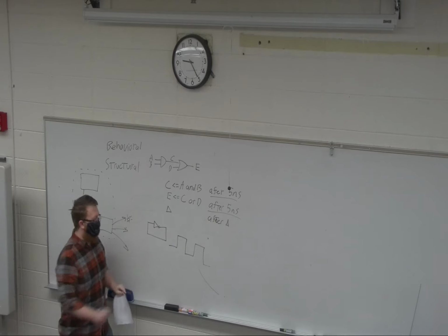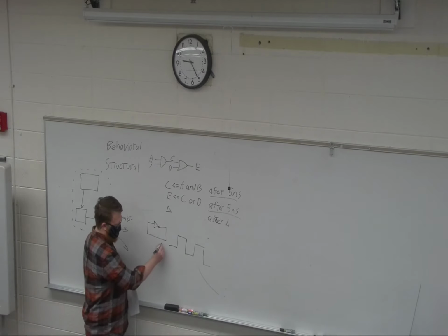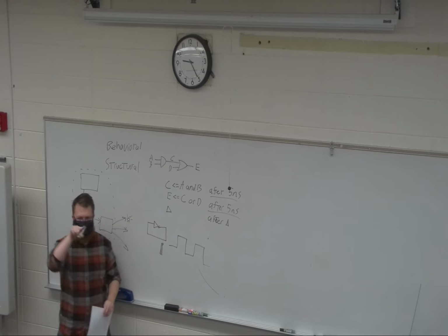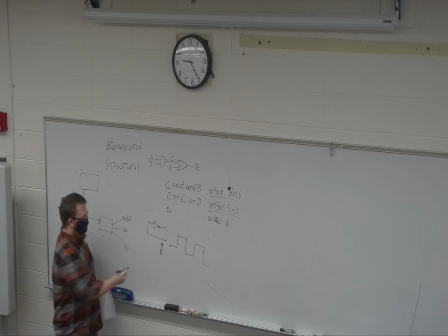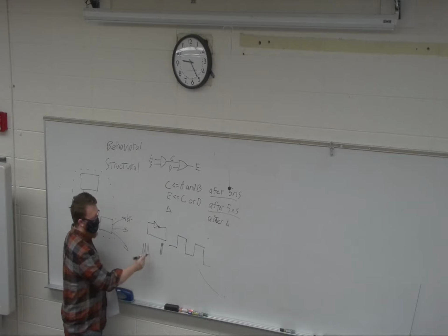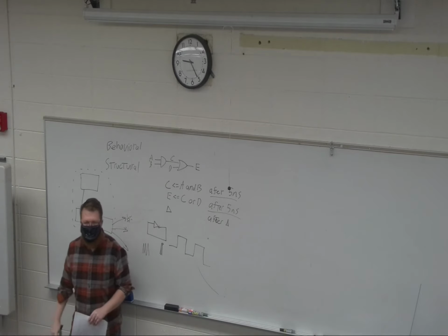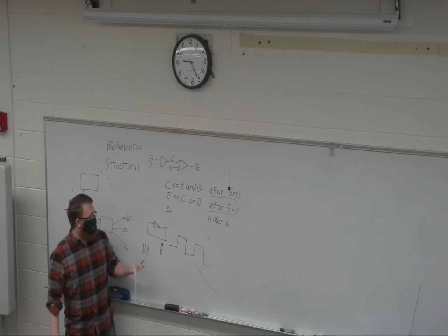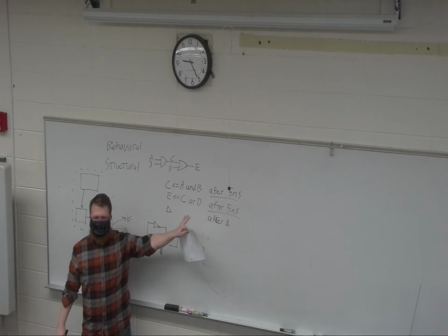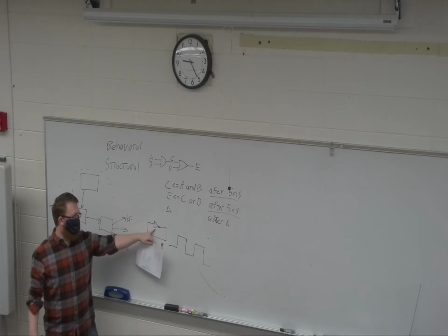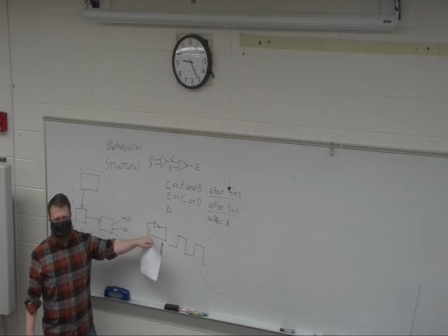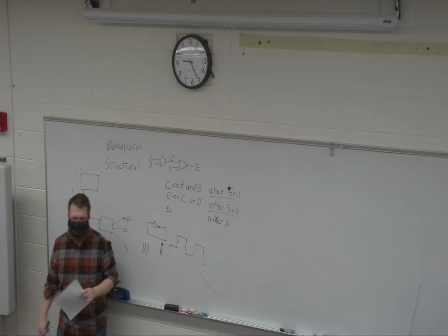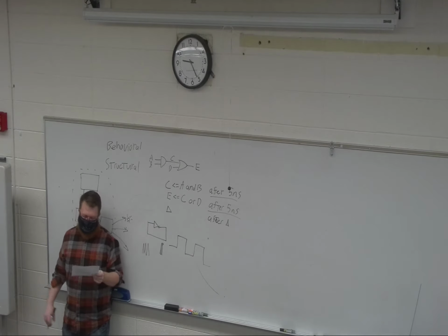And in simulation, it's going to look like a pretty good clock because I've said after 5 nanoseconds. If I don't say after 5 nanoseconds, it's going to be even worse than I can draw, right? It's just going to be a constant blur of up and down. And because it uses single data points, it's actually going to probably look like a squished together sawtooth like that. So trying to get the propagation delay can matter. And we actually do use circuits similar to this. They're a little bit more complicated to make sure the timing makes sense, but we actually do use similar circuits like this in PLLs, which is how you generate clocks.